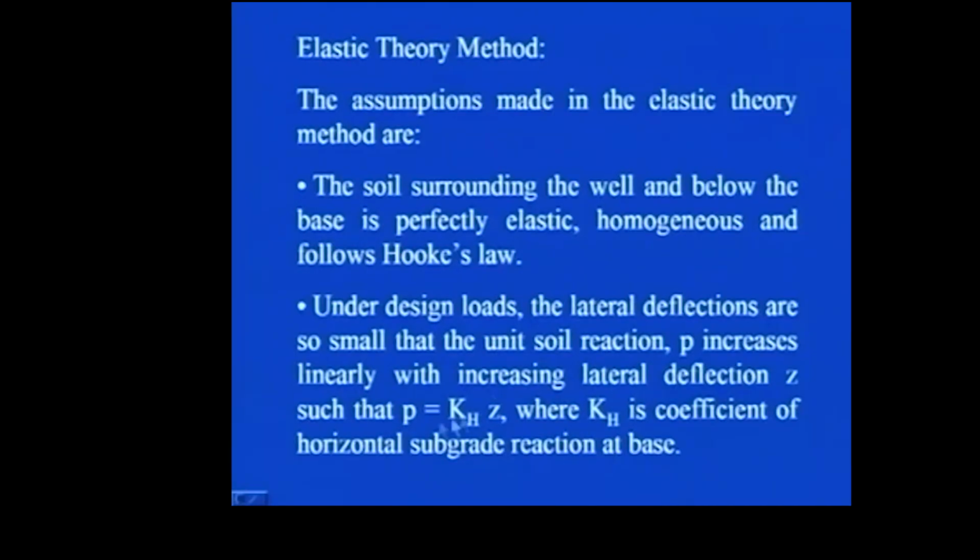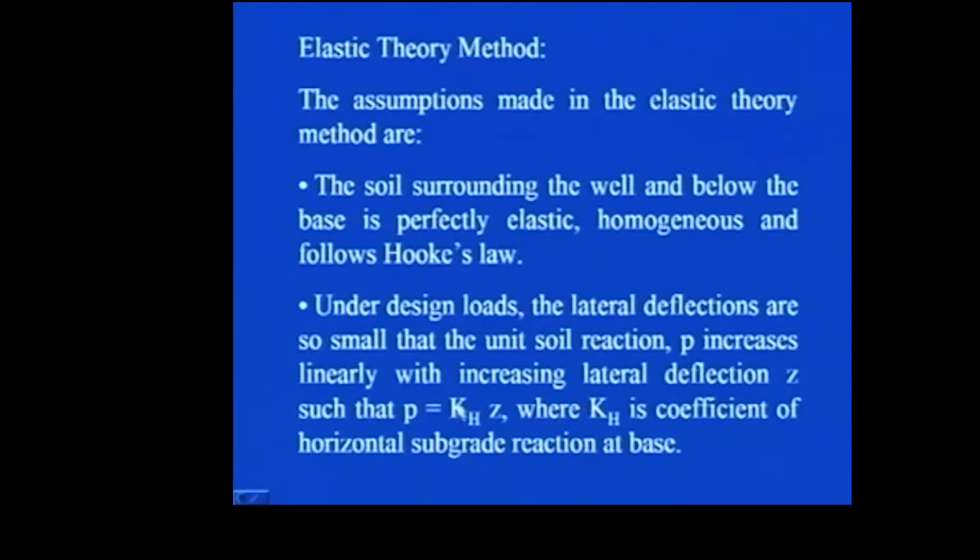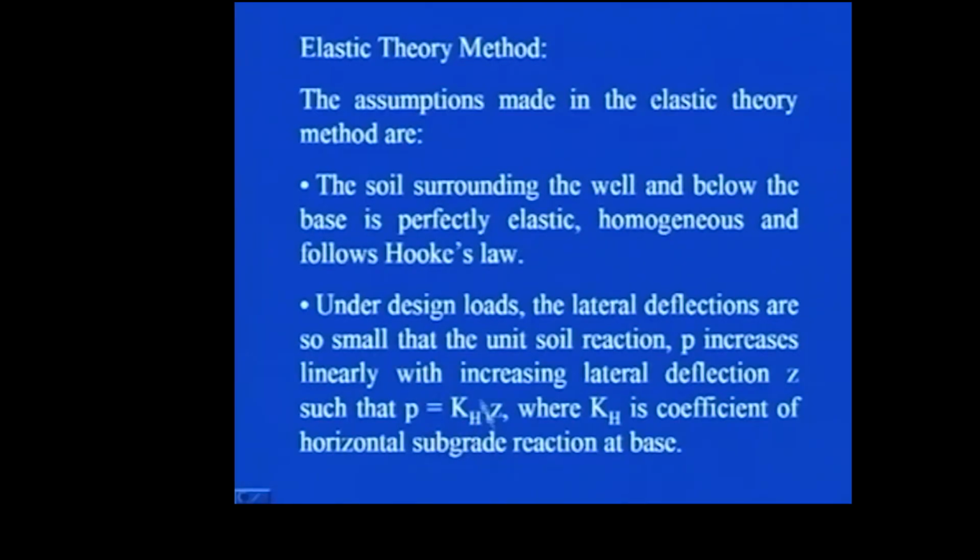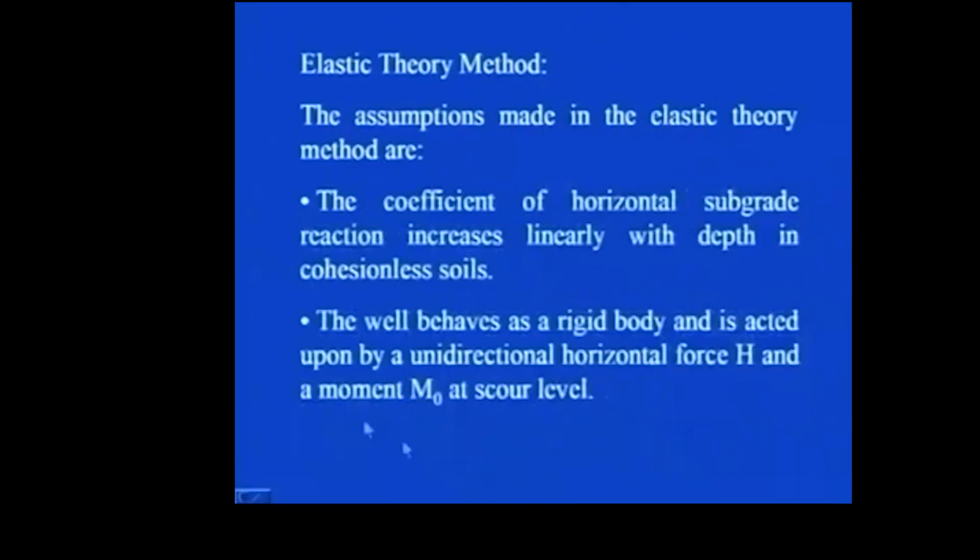So, this is an important assumption that P increases linearly with increase in the lateral deflection Z, and that coefficient of proportionality is represented by the coefficient of horizontal subgrade reaction at base, KH.